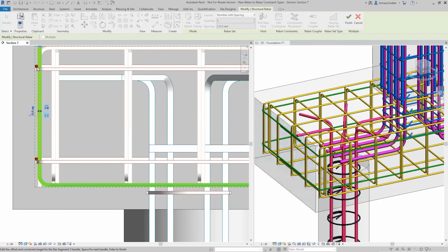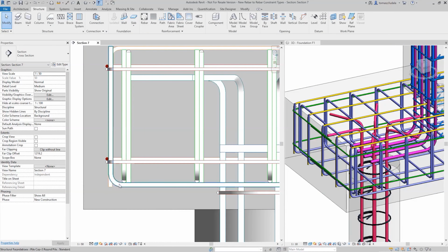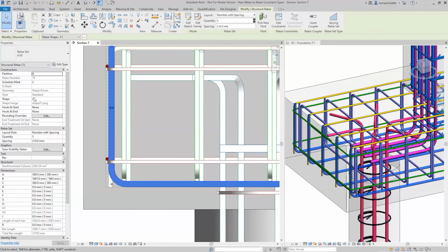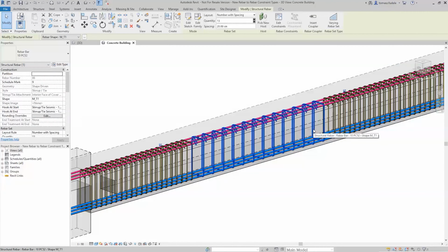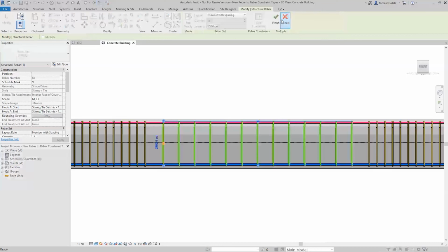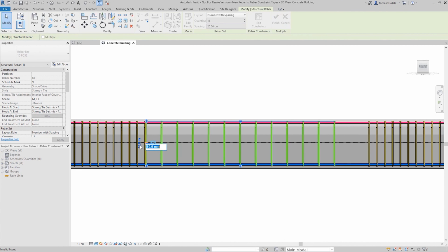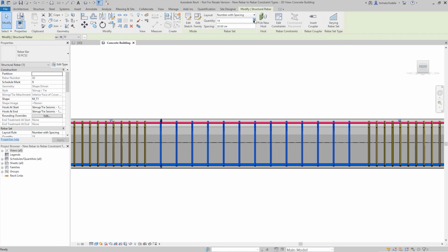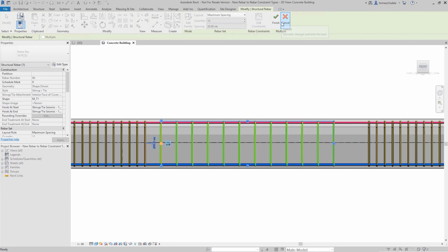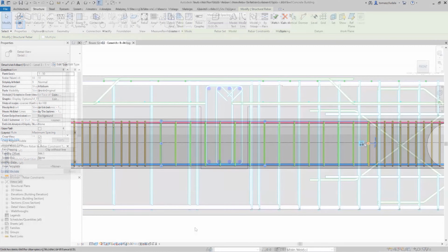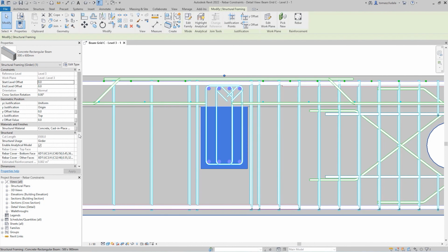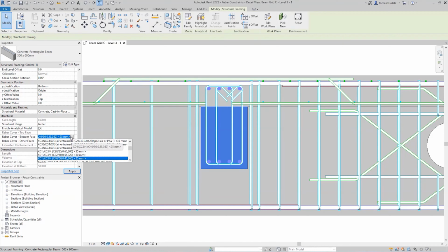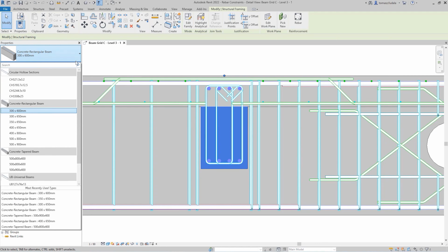Using in-canvas tools, you can place rebar more precisely with the Graphical Rebar Constraints Manager. The user interface highlights each rebar segment that can be constrained, along with the available targets. That makes working with rebar constraints easy and intuitive. The snap constraints maintain their relationship when you place, move, drag, or copy rebar. Let's imagine a situation where you need to slightly adjust your concrete cover, or the element section dimensions must be updated. With the properly defined rebar constraints, this update would take you only a second.